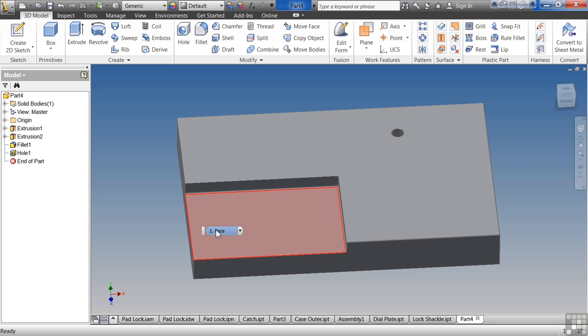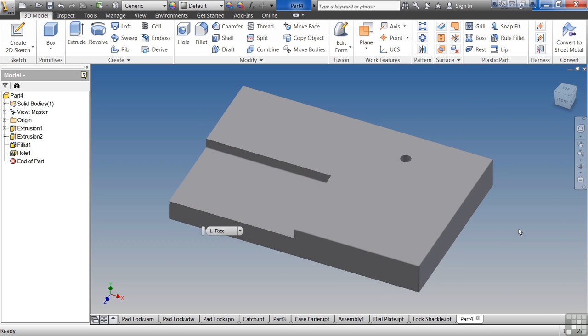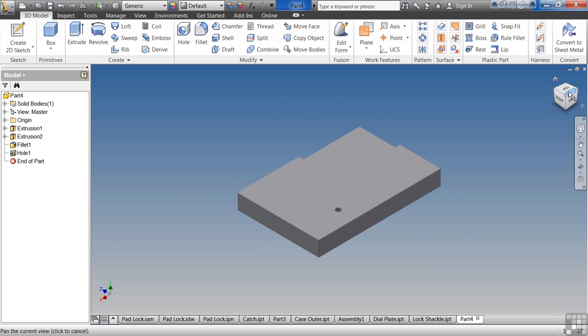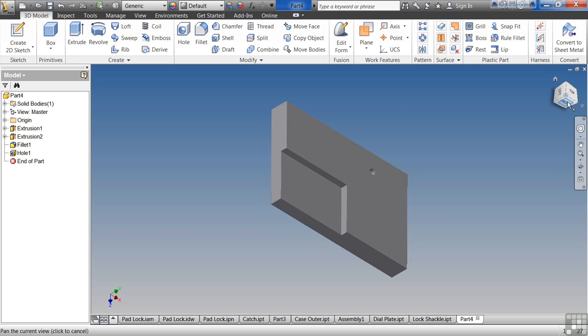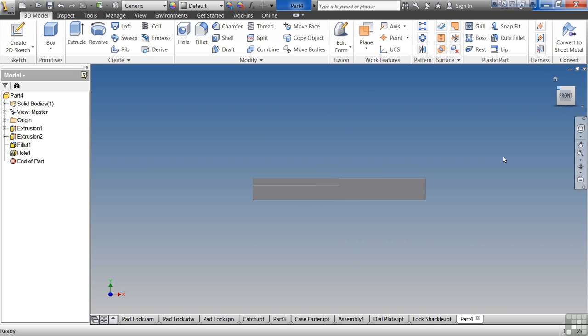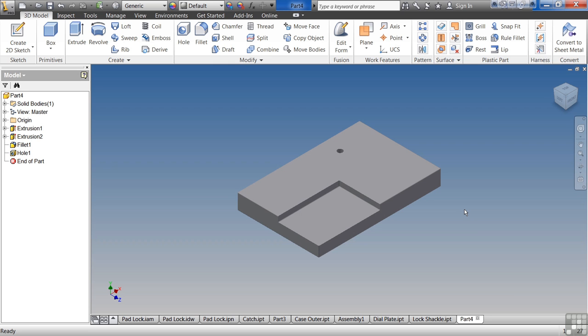And remember that our base part was a big square, big rectangle. So it was very easy to determine what it was going to be. You can play with zooming around a little bit here and look at your first part and see how Inventor plays with it and works and gives you what you need. Remember that the largest goes first, second largest next, order of importance. Size does matter in Inventor, so you start out with the largest object and work your way down, hole being the smallest, so I'd place it last.